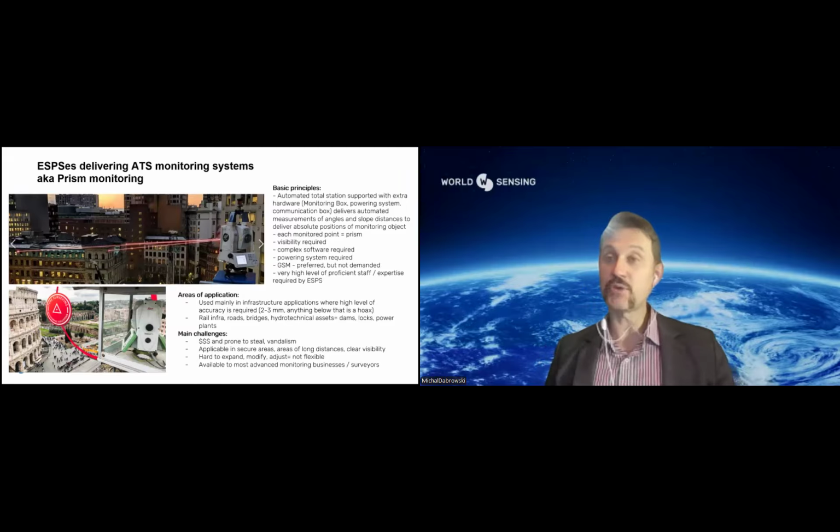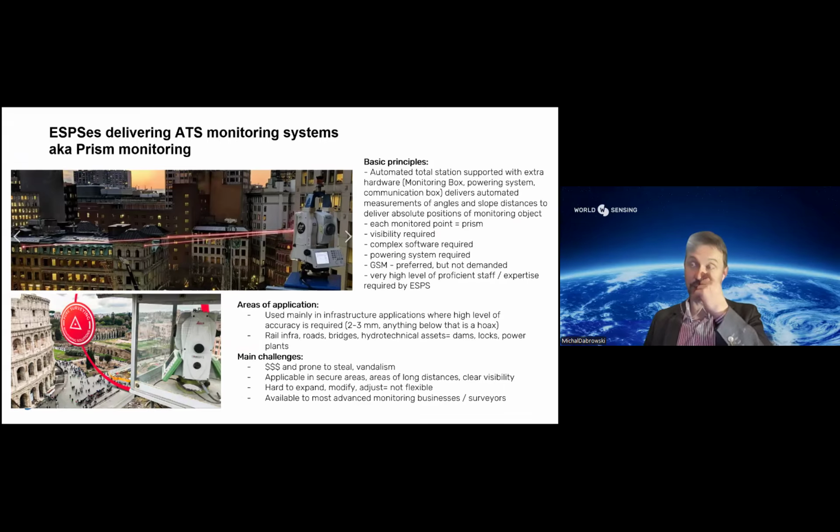As much as we can argue that a half-second robotic total station can obtain position down to 1 millimeter accuracy, there are many factors in between: resection, measuring to your control prisms, making rounds, and changes of ambient temperature.